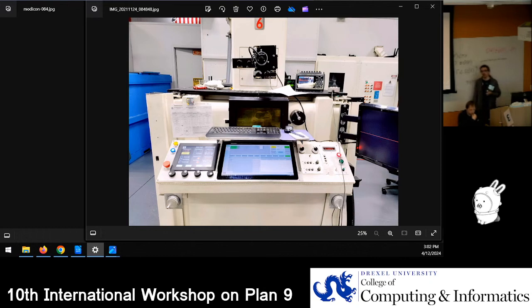Today, Modbus is actually very primitive, but it's still an open standard, and pretty much everybody supports it out of the box nowadays. MQTT is sort of displacing that as your standard little protocol to communicate process data between controllers. So that would definitely be a place to look today. Yeah. I haven't looked at it myself yet, the technical part, but eventually, yeah, it's something else.